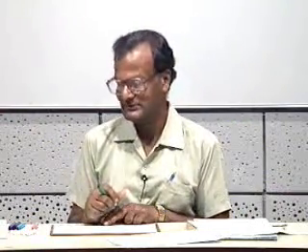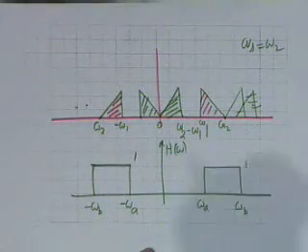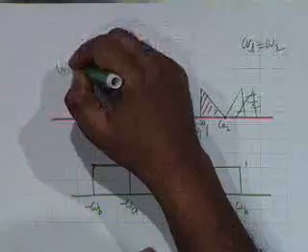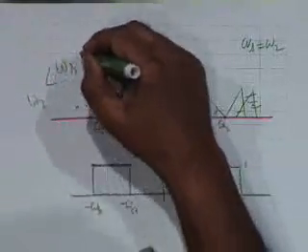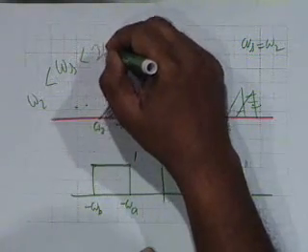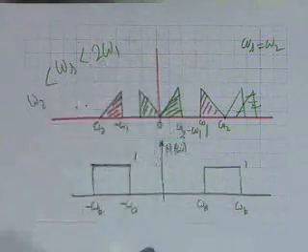And that shows one of the limitations of this kind of sampling. Not quite limitation, but a practical wisdom. Your omega s should not be exactly omega 2. It should be slightly higher than omega 2. Omega s, as you recall, should be greater than omega 2, less than what? 2 omega 1. And therefore omega s can lie anywhere between the two.